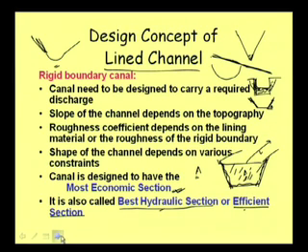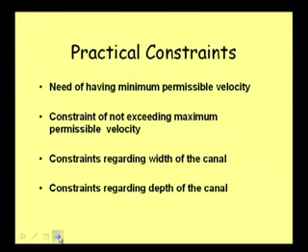Well, but it may not always be possible. What will make this the best hydraulic section, we will discuss definitely, but it may not always be possible to design the channel or canal as a best hydraulic section. Suppose for a rectangular channel, the best hydraulic section is where the bed width is equal to twice the depth.